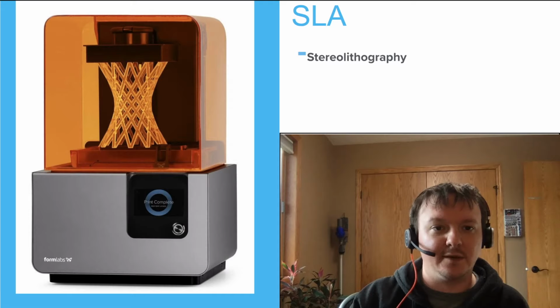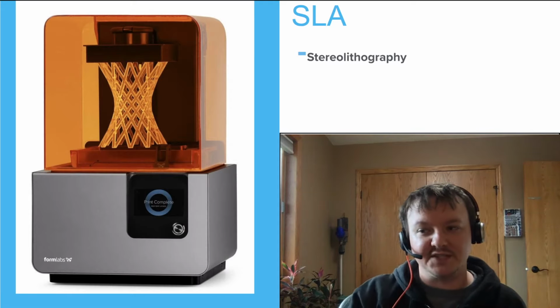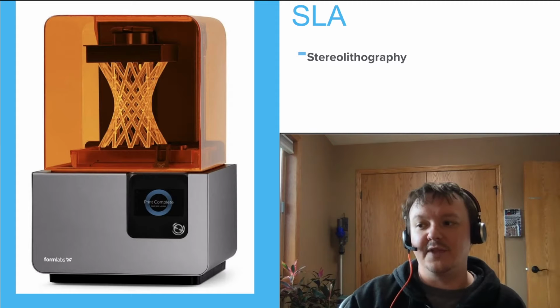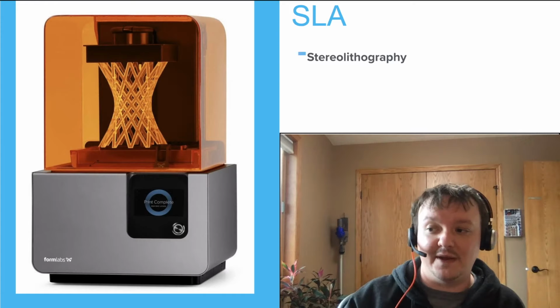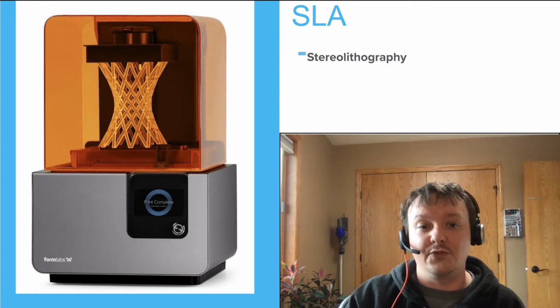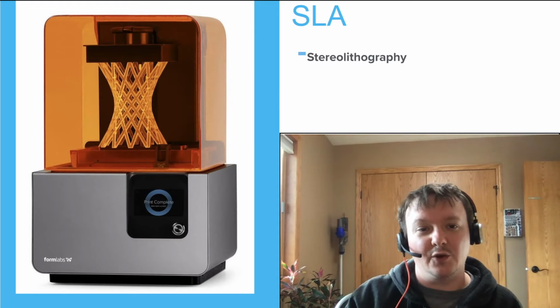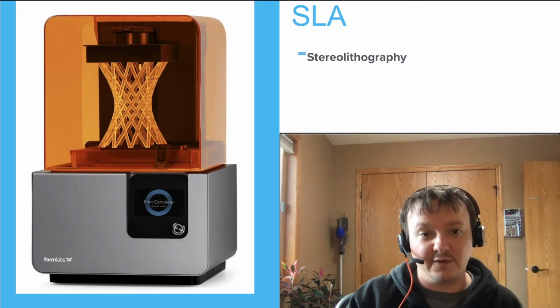So basically, that large portion on the top sits in the bed of resin. They shine light on it in whatever pattern you want for that layer. Then the bed moves up slightly and you do it all over again. The big feature of this is you can get very, very high resolution. If you're doing inch-tall miniatures for your D&D campaign, this technology works really well.